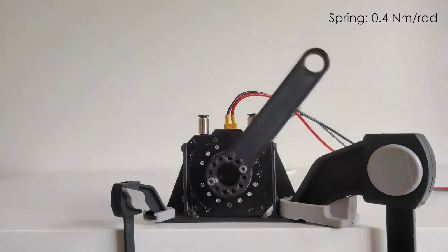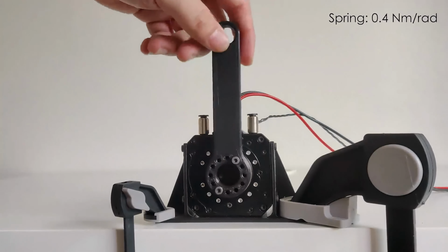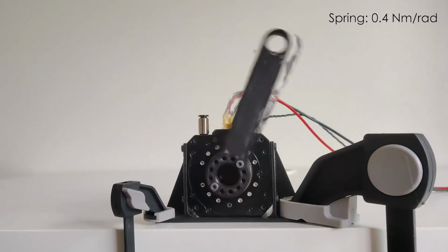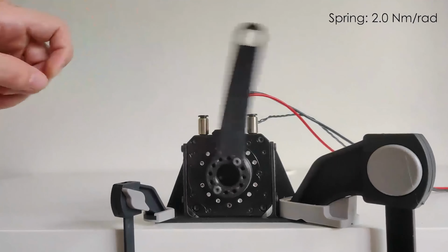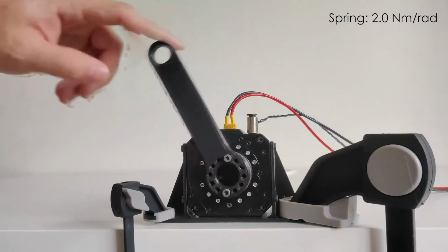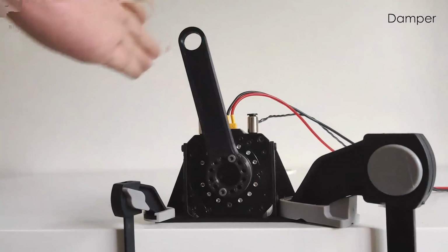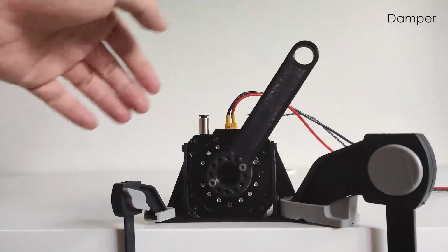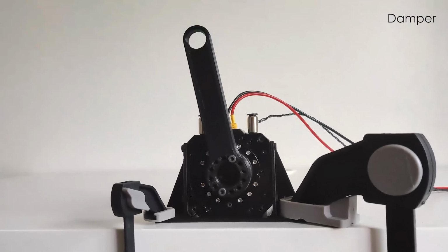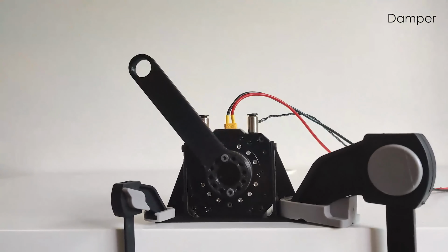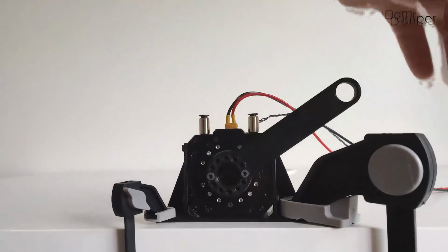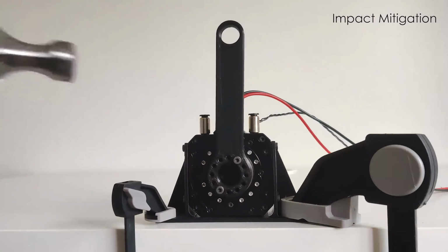Goal position defines the equilibrium point for the virtual spring system. The direct force P gain acts on the resulting angular position error. Goal velocity functions as the target velocity for the virtual damper. This is blended into the control loop via the direct force D gain. Goal torque acts as a feed-forward command that integrates directly with the underlying current loop PID gains.